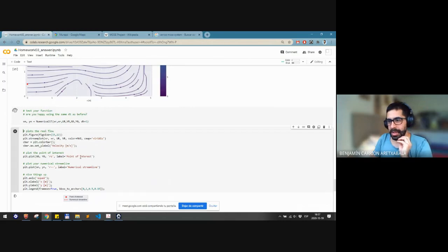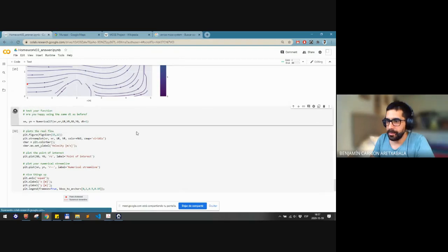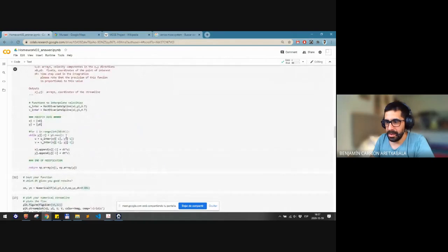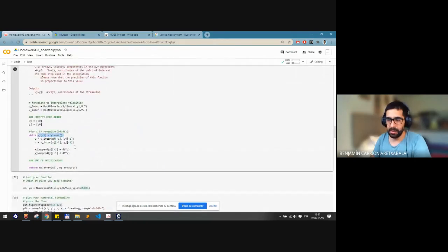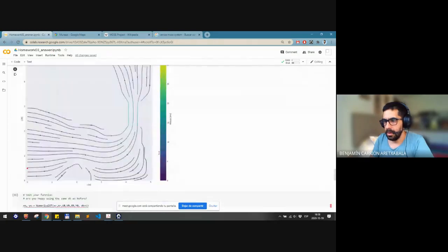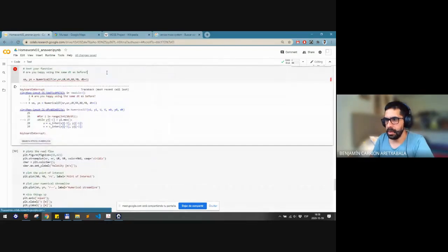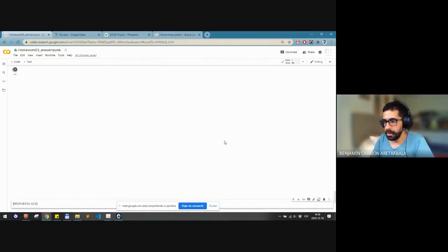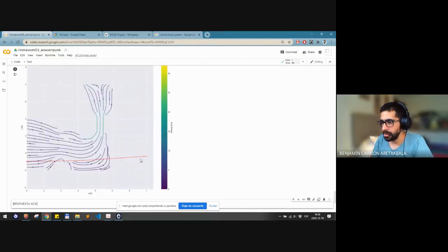It took me a while, but what's happening there is that it's stuck in a loop, because I put this condition to break, and with a very large time step, the streamline doesn't go up, so this condition never happens. So maybe if I use this one as we did before, then it should run with a very large time step. Then we can plot it. It should be rubbish, just rubbish, right?